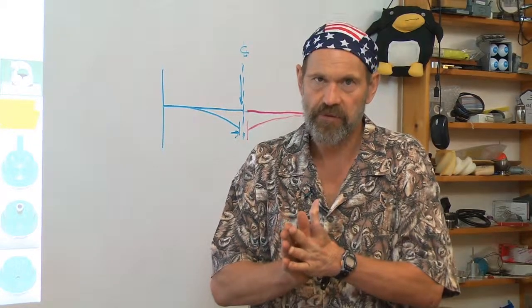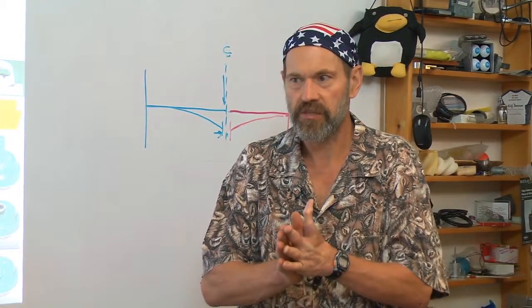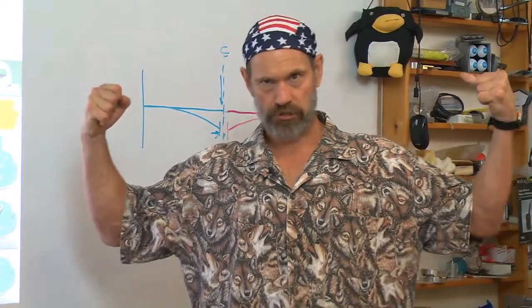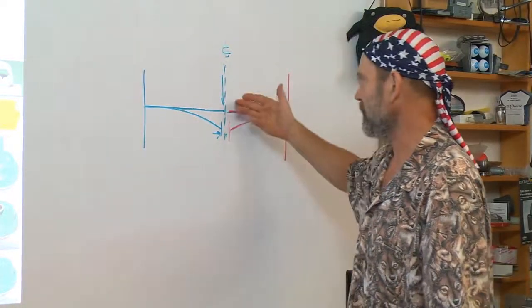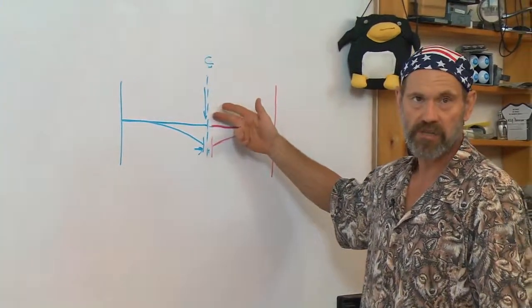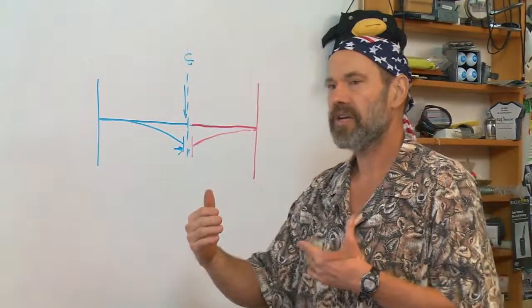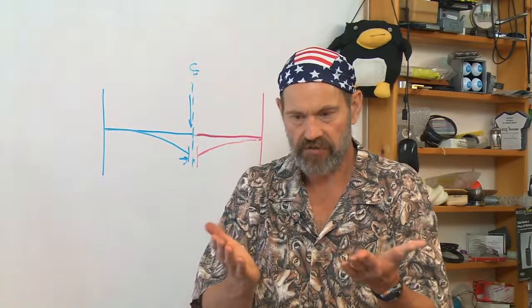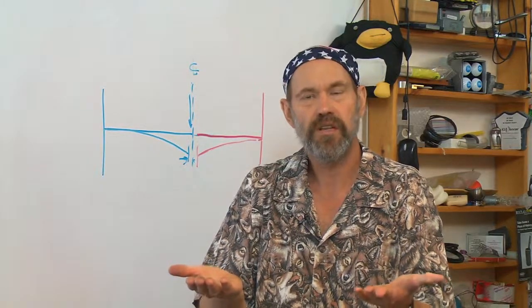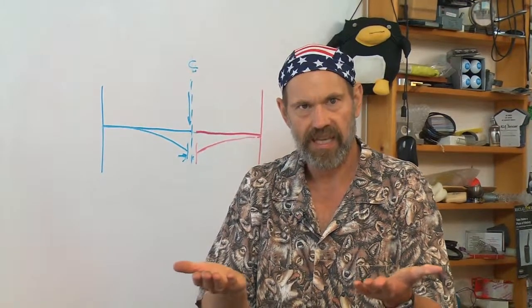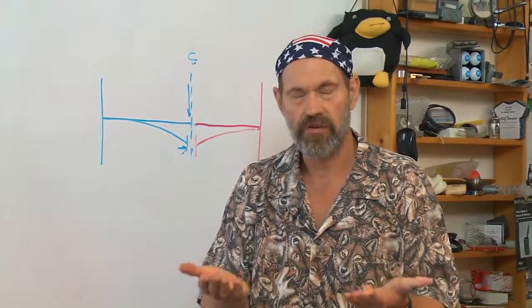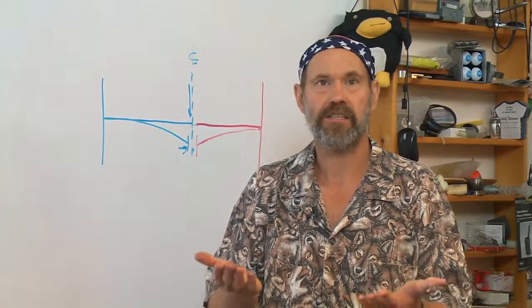If they are a problem for your machine, you ask yourself the question, well, how can I make them go away by either just making it much stronger, stiffer, but that doesn't always get rid of the parasitic motion. For example, here, it's just a function of the geometry. Or how can I use reciprocity or make a structure a mirror image of itself and use one parasitic motion to cancel another? That's a very, very powerful part of design, that use of reciprocity and canceling error motions.